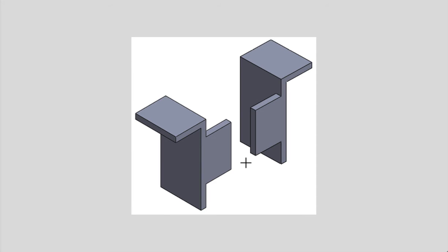As well, there's a concept that we use to save polygons, and it's called extrusion. And basically, an extrusion creates an outline of a shape, and then that outline becomes like a mold, like a cookie cutter, and then you push, literally you push the material through the cookie cutter and you create depth to that model. You'll see in SketchUp, that's a very common way of building models. So when you're working through the tutorials, the very first thing you do is extrude a lot of things.